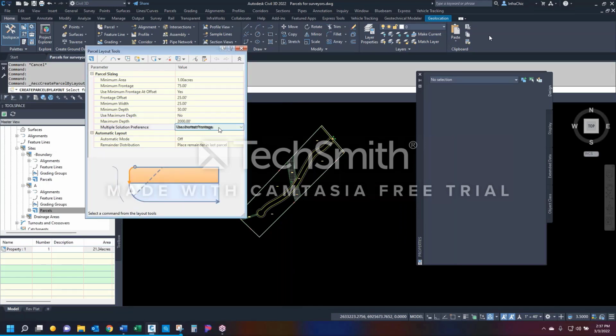Maximum, let's see, use the shortest footage or the smallest area. Okay, automatic could be on, but I'm going to leave it off. Place the remainder in the last parcel, redistribute the remainder, or create a parcel. I'm going to place the remainder in the last parcel if there's excess left over. So we got that set up.